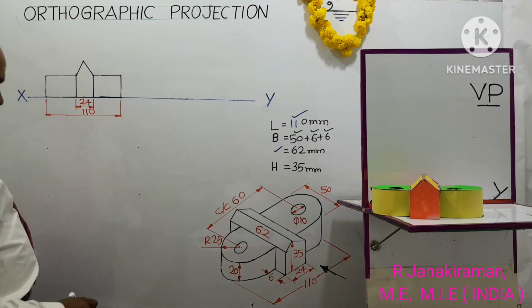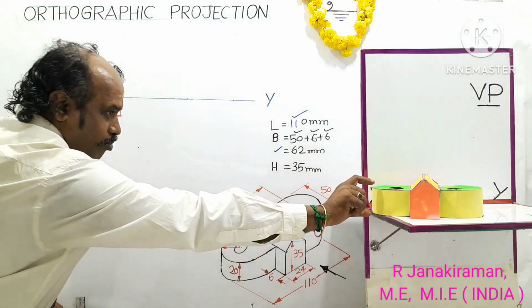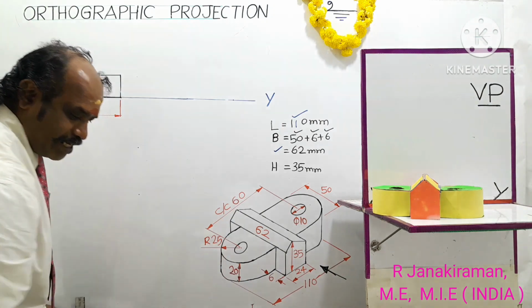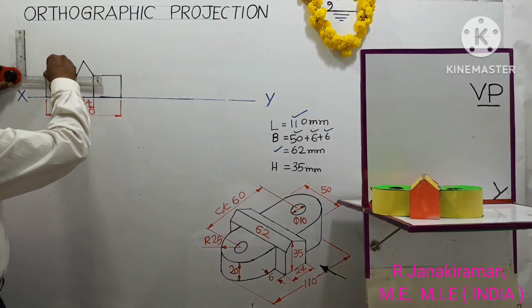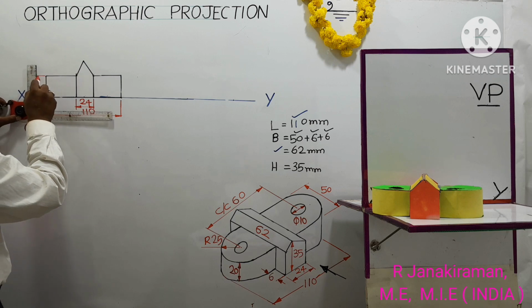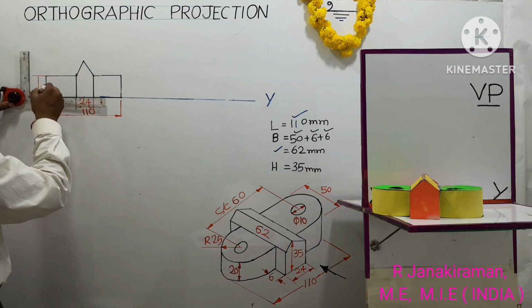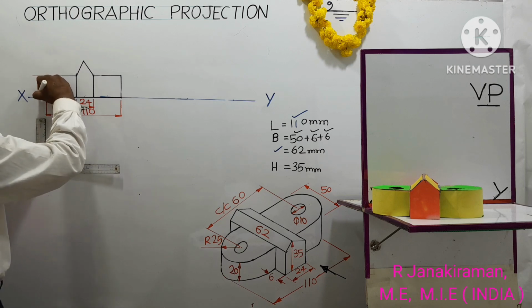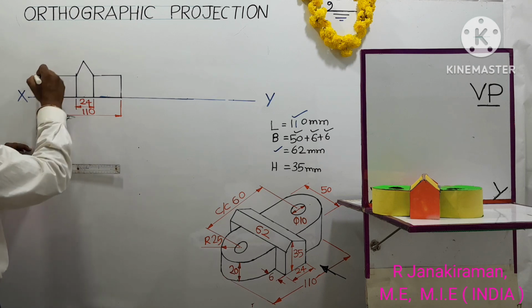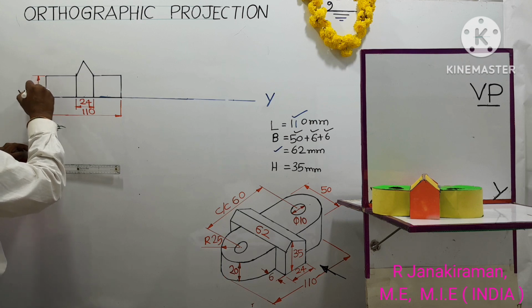Okay. So now I'm going to mark the height of your yellow portion, which is 20 mm given in the diagram. So draw the extension line, draw the dimension line, put narrow arrows, shade them, and you can write the height of this base, shown yellow in color, as 20 mm.